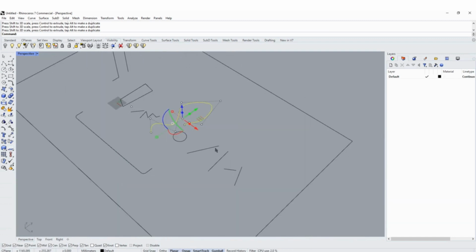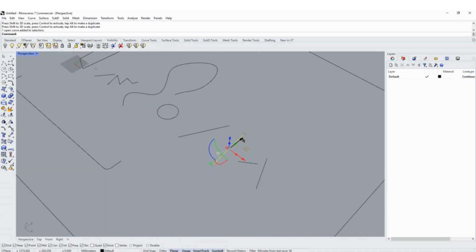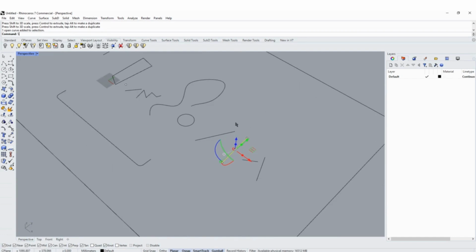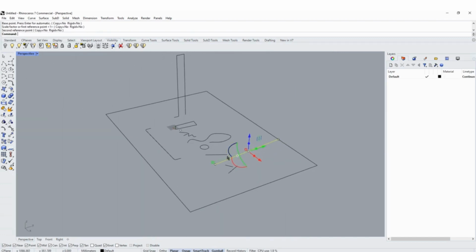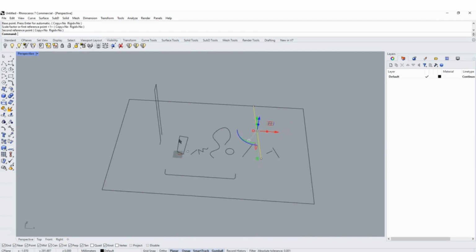So let's say that I want this line of mine to actually start from here, but not end there, but rather end right at this line, then I can scale. I just want 1 dimension scale, and I will use as reference point this one, and then I just drag it and drag it until it hits right over here. So now I can just scale. So these are different ways to shape, move, and form your different elements.